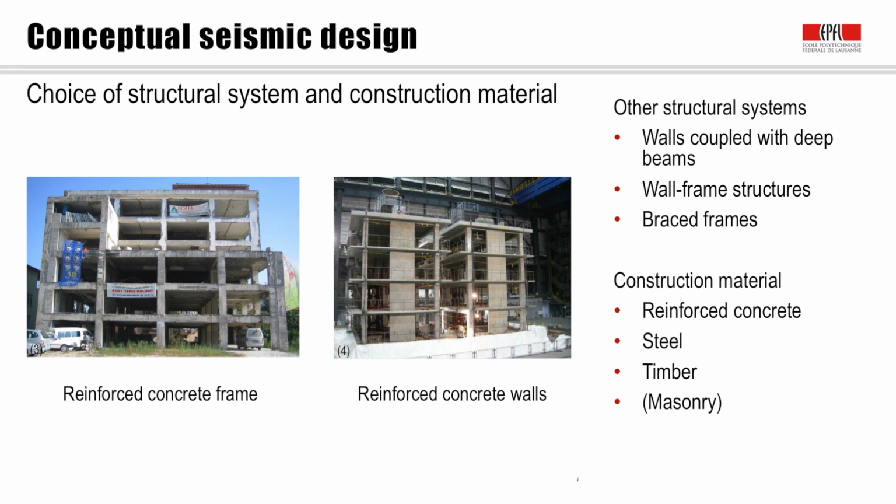All of these materials can behave well during earthquakes, provided they are designed in such a way that the structural elements have a sufficiently large displacement capacity. Masonry can behave well if it's reinforced.